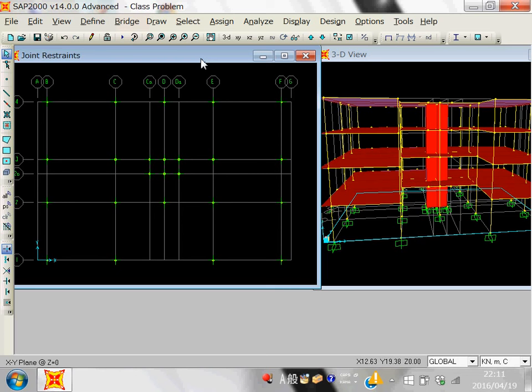You understand? For example, if there is a stair and a beam is supporting a particular stair, you can consider the load of that, because you know the tributary area, you know the length of stair, so half the length multiplied by the load per unit area will become the load per unit length on the beam. Just add it.